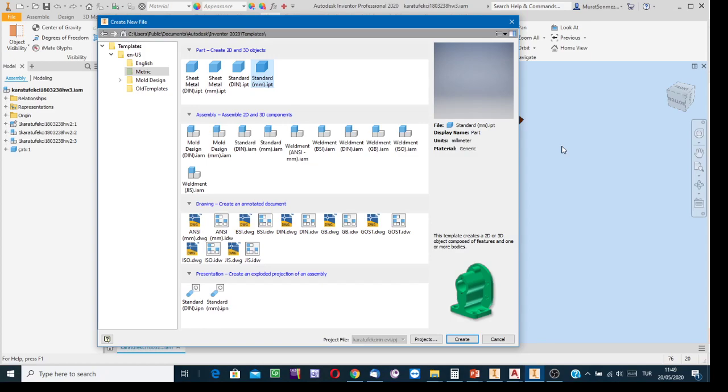But at the dimensioning stage, after drawing or creating the views, if it is a mechanical engineering product, aerospace engineering product, or petroleum chemical engineering product, then show the dimensions in millimeter in metric unit system, inch in British unit system. But in architectural products, say architectural drawings or civil engineering drawings, the commonly used unit of measurement in the metric world is centimeter. In the British world, it is foot.